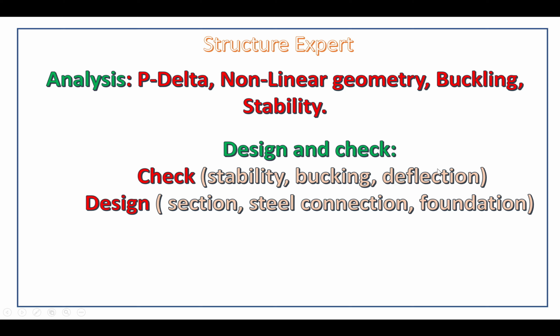This structure we concern about deflection, and for the strength is no problem, because you use the larger element to resist bending, to resist shear, to resist the actual force. But after you design the strength design, you have to check about the serviceability limits, that means your structure is suitable in deflection, not over deflect. Okay, you have to check it.